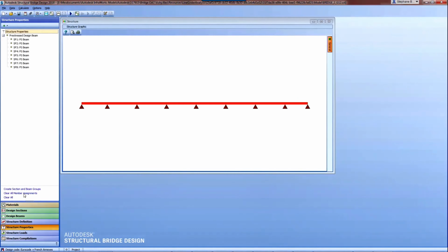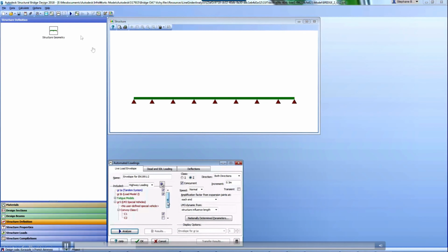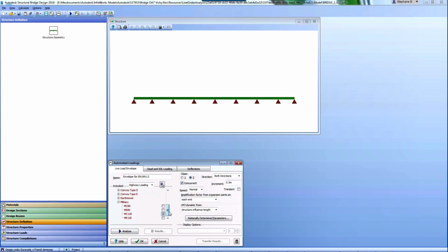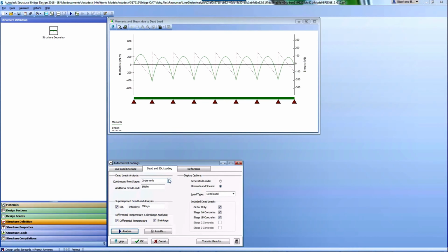And here, when I look at everything, I will set here in the element a new live load envelope. So here, military. Here you see you have all kinds of elements in highway or in rail, and I will have a fatigue model three. I have to rerun, and I tune a little bit the dead loads I had here, and after I will reload again the live load envelope.